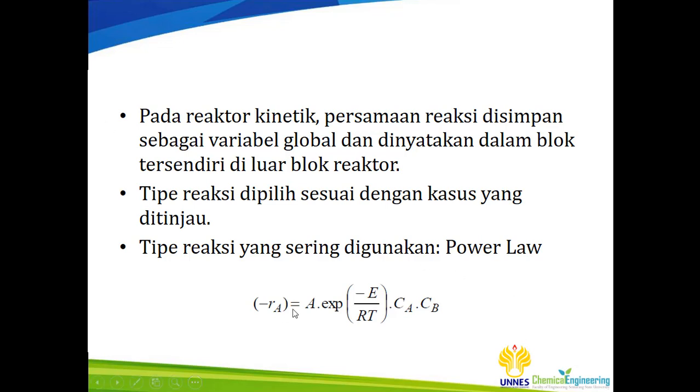So this one is the power law equation. Let's say A plus B will produce C, and this is the kinetic reaction equation: the kinetic reaction rate is A times exponential of minus E per RT times concentration of A times concentration of B. So this one is the common equation used in the power law.